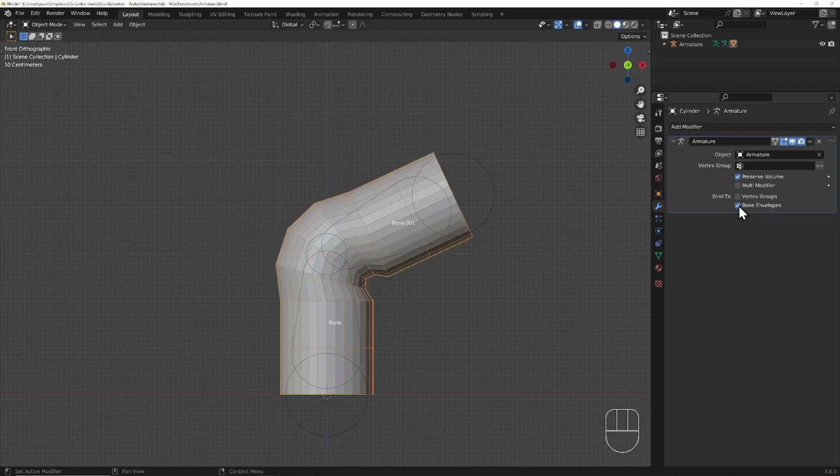You can immediately see the difference in the effect because this ignores the weight distributions assigned to the vertex groups and uses the envelope's own fall-off instead. Using the preserve volume setting will create different results. The multi-modifier option works best when there are more modifiers in the stack.